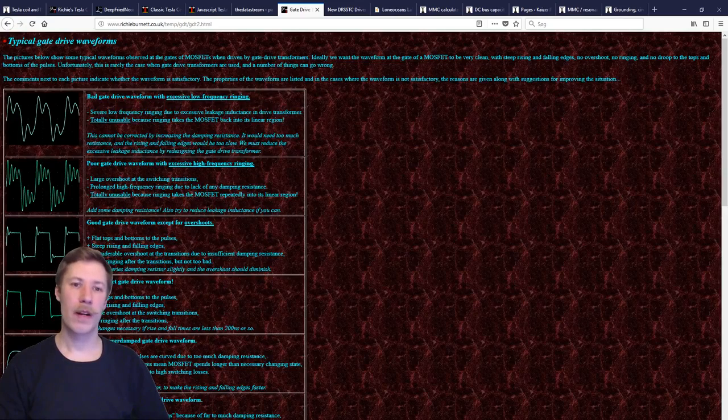The primary coil is not that sensitive, as it has a much lower impedance, and it's not that picky about the surroundings, because you can say that the primary circuit is something that we just dump a whole lot of energy into, and we kind of force it to behave the way we want. But the secondary coil is much more sensitive to surroundings. So clearly you should have it all assembled, as close to the running setup as possible.